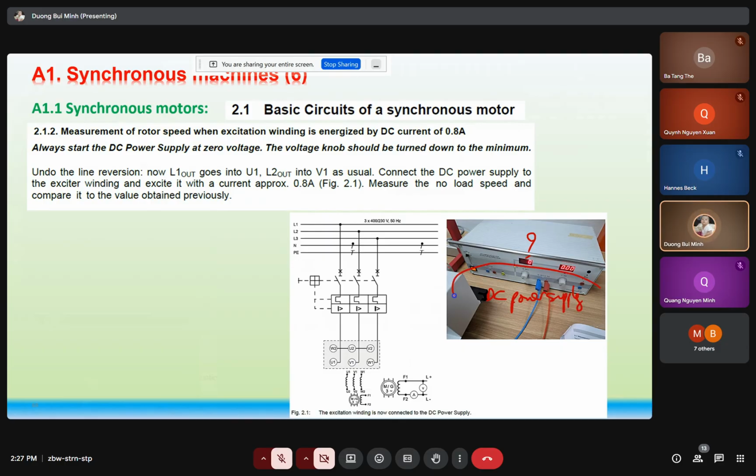Yeah, of course, we use a DC power supply to supply the voltage and current into the rotor winding of the synchronous machine, right? So if we have IDC or we have IR, the rotor current, we can generate the rotor magnetic field. And if we have phi S versus phi R, you can get induced torque, right?